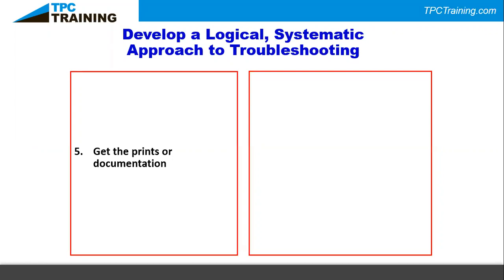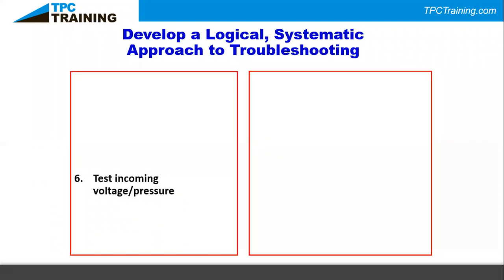So I think it's going to be a really important distinction to say you have to have up-to-date schematics and really good quality meters. Not something you might buy off of a random wholesale warehouse, but a really good quality, reputable meter. Okay. So once you've got all that, you're all suited up in the PPE, now it's time to really take that approach inside the panel.